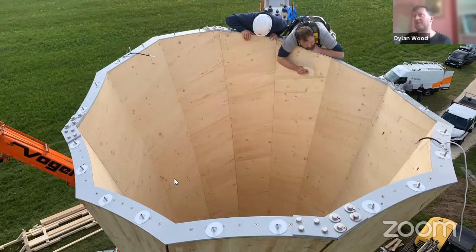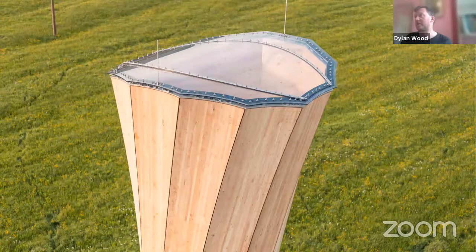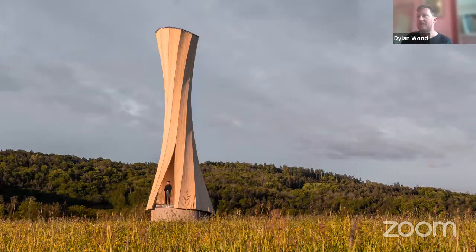And this results, of course, in a structure that is almost completely wood in its load-bearing capacity, other than this very, very thin 10 millimeter steel ring at the top, which prevents ovalization and also provides an interface to connect to the polycarbonate roof, which protects the inside sheltered area. And this results in a very quick assembly on site of a structure with a very unique geometry.